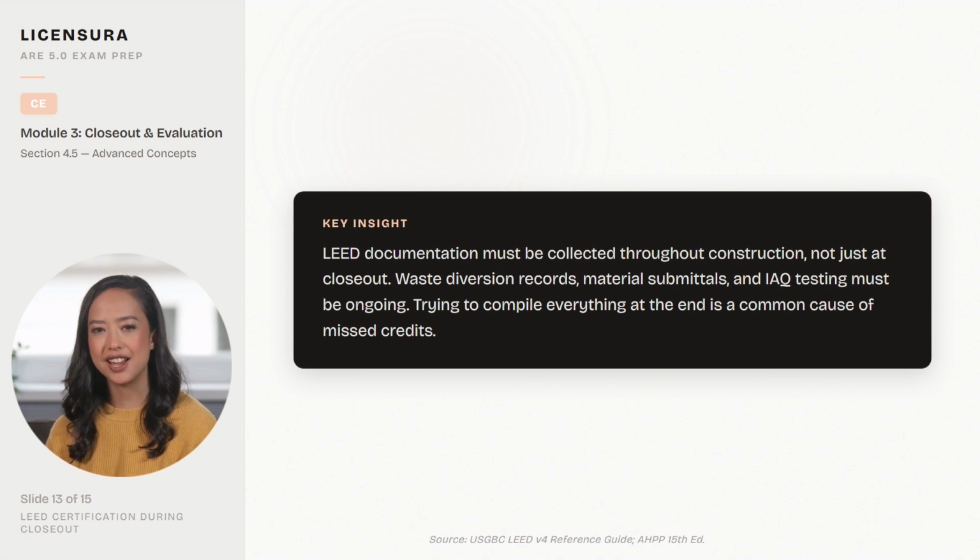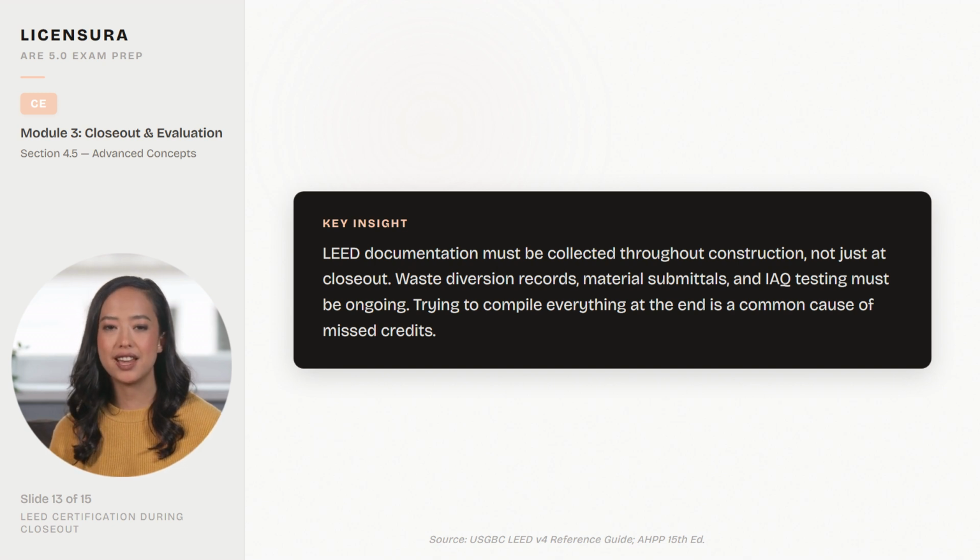Here's the key insight: LEED documentation must be collected throughout construction, not just at closeout. Waste diversion records, material submittals, and IAQ testing must be ongoing. Trying to compile everything at the end is a common cause of missed credits.